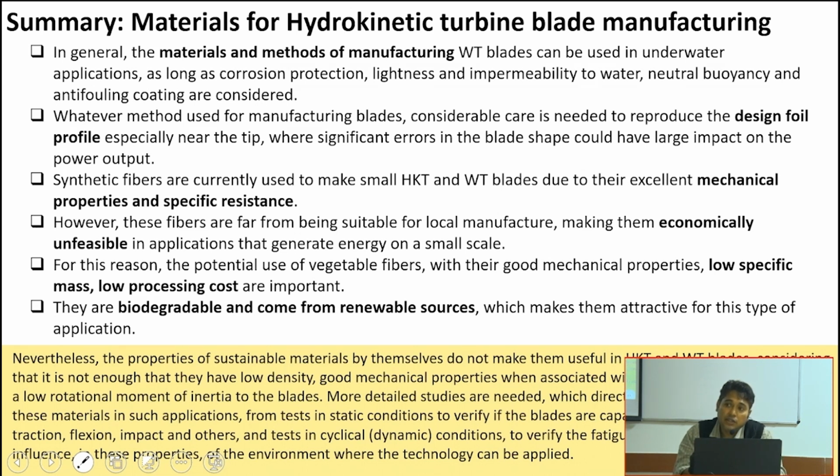The wind turbine's size will be bigger. The hydrokinetic turbine will not be bigger, because, as I have already told, a hydrokinetic turbine will be installed in small water depths of 2 meters, 3 meters, maximum 5 meters. You can go for higher water depth, but the size of the hydrokinetic turbine will be comparatively less. Even if you look at a similar design of a hydrokinetic turbine and a wind turbine, they will look the same. But size wise, the wind turbine will be bigger and the hydrokinetic turbine will be smaller.